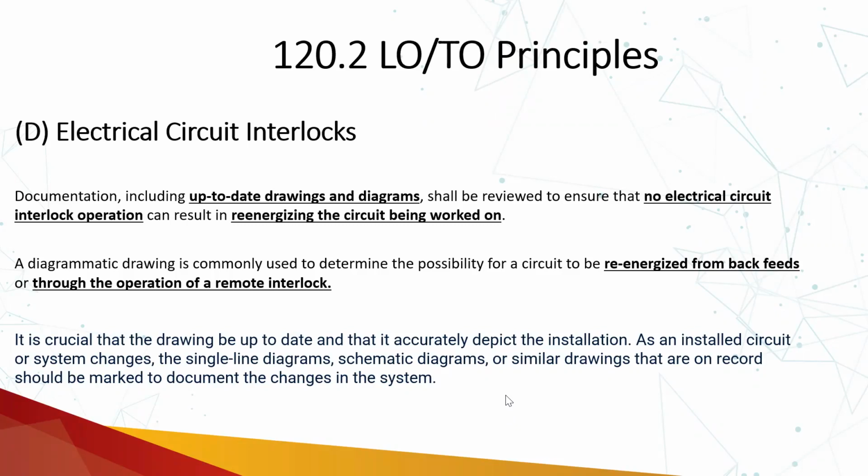Yes, so this is related to electrical circuit interlocks. Those need to be up to date on the drawings and diagrams which are available, and the qualified person should take into consideration that nothing can cause the re-energization of the circuit.